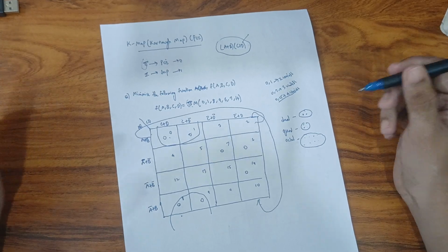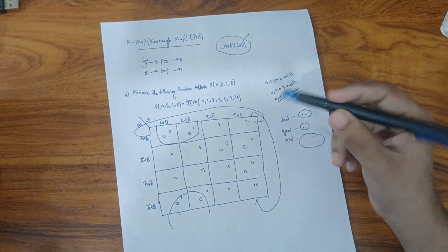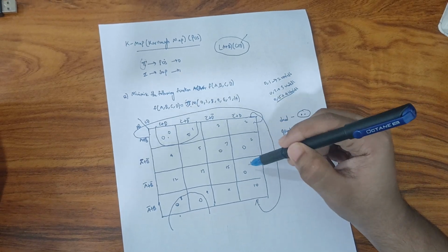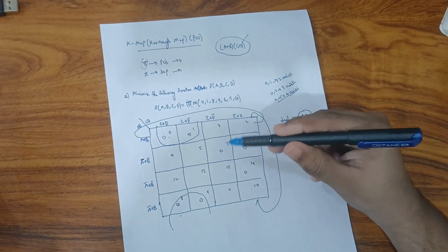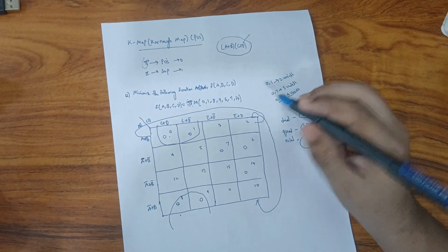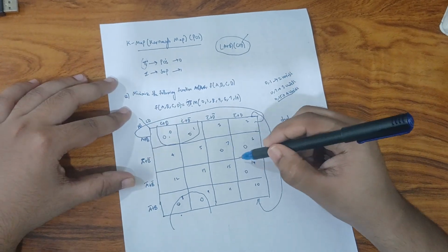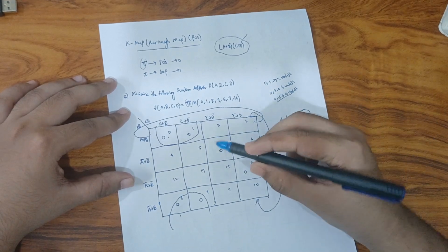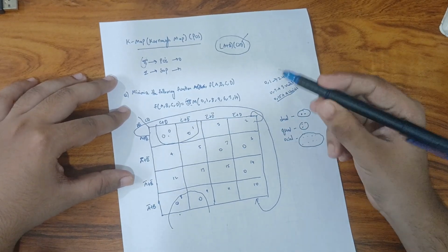Now let us check the other minterms and see if there is anything common to group them. So you can basically see that there are 3 minterms which are almost adjacent to each other. So what do we do here? You can't take 3 elements at a time, nor can you take diagonally. Some of the common mistakes people make is taking these diagonally, but this is absolutely a blunder. You should never take it diagonally. You should always consider it horizontally or vertically.